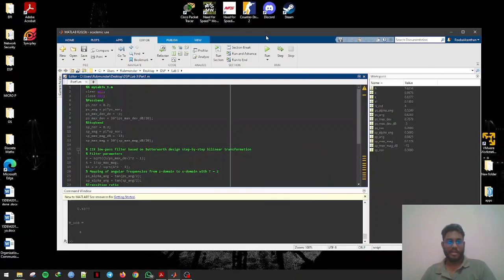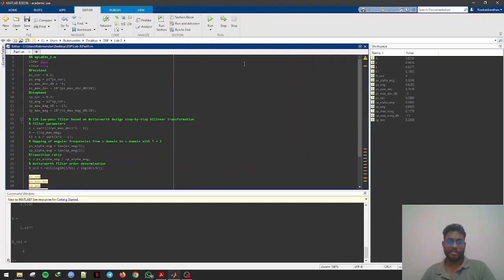The infinite impulse response filter is a type of digital filter that has a feedback component, unlike the FIR filter that only uses feed forward coefficients. This feedback loop in the IIR filter is responsible for the infinite response, which means the impulse response does not decay to zero after a certain time, as opposed to FIR filters.